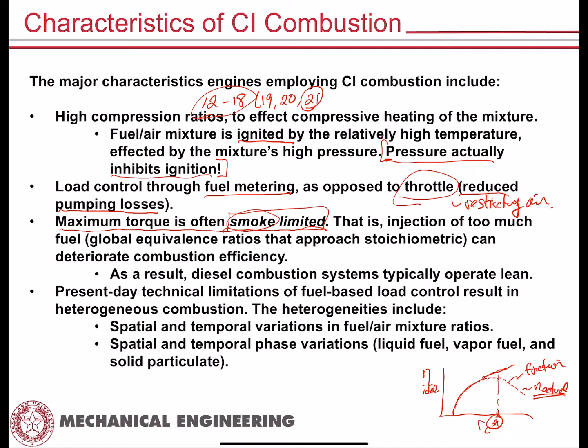And you can actually generate so much smoke that it begins to deteriorate your combustion efficiency, and your engine torque can start to go down, right? So a lot of times people will ask me, why don't diesel engines operate at stoichiometric conditions? And the answer is, well, because they can't produce enough torque, right? I can produce more torque at a lower equivalence ratio than if I were to try and run that engine at stoichiometric conditions.